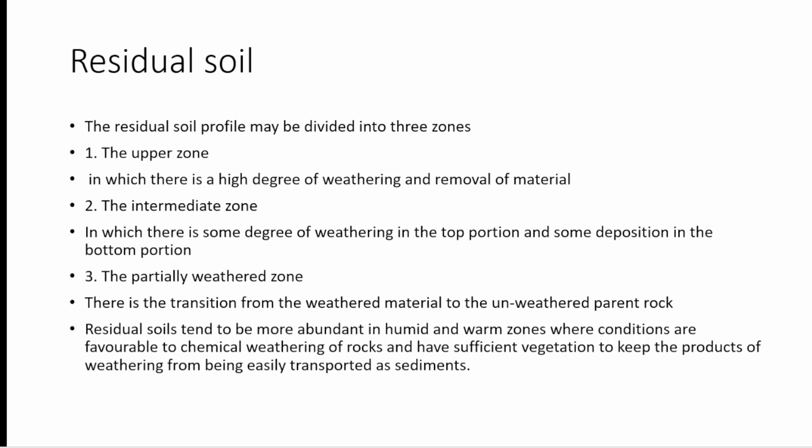Residual soils tend to be more abundant in humid and warm zones where conditions are favorable to chemical weathering of rocks and have sufficient vegetation to keep the products of weathering from being easily transported as sediments. Residual soils have not received much attention from geotechnical engineers because these are located primarily in undeveloped areas. In some zones in South India, sedimentary soil deposits range from 8 to 15 m in thickness.